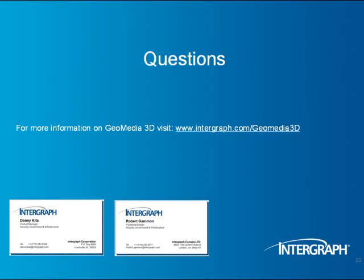Danny, if you could handle this one too. There's one here about, do I have to set up the 3D representation of feature classes for each project? Oh, okay. Yes, I will. For your master database, what we were showing in terms of the decisions you would make on how you want to represent a feature class, once you've done that, you can save that out to a library. So then the start of any new project would begin with the first step of importing your library, which would have all those feature class settings, so you really wouldn't have to do it more than once.